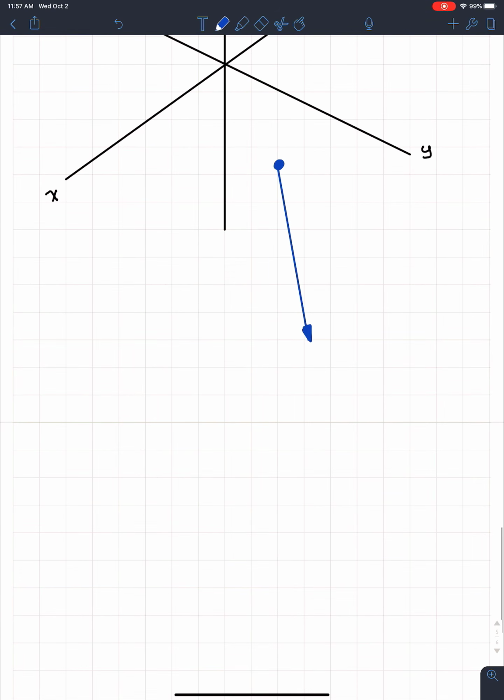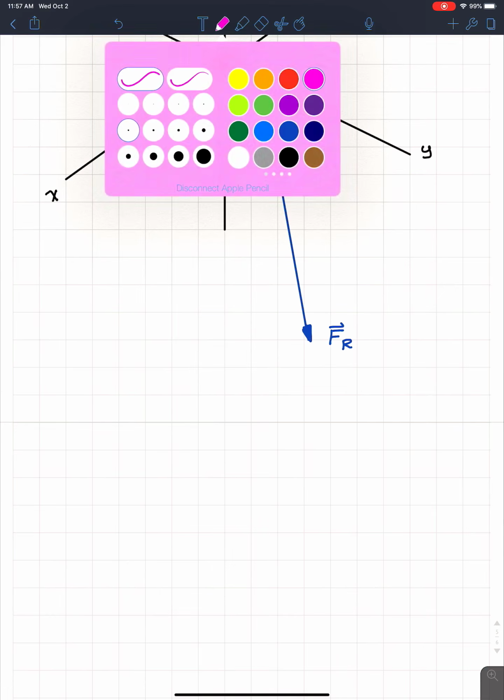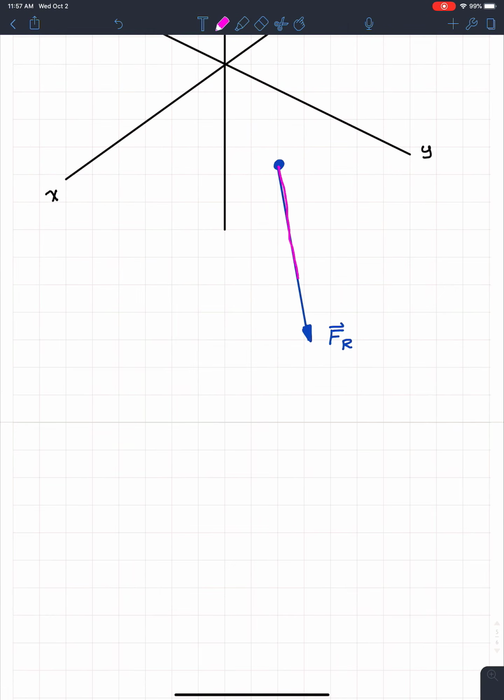So this right here is our resultant force, and we had a moment vector that ran in the same direction. So remember, that's what a wrench is, when the moment vector and the force vector go in the exact same direction. So this is M_R parallel. That one's not the resultant moment, it's a component of the resultant moment.